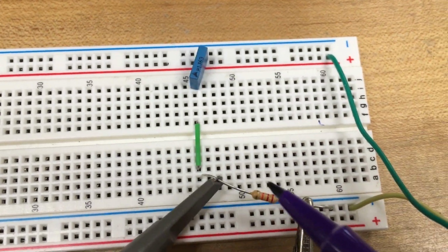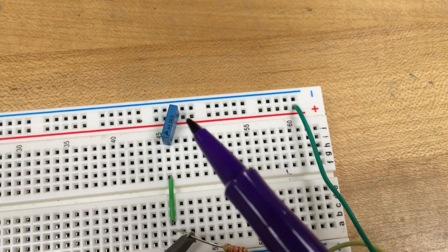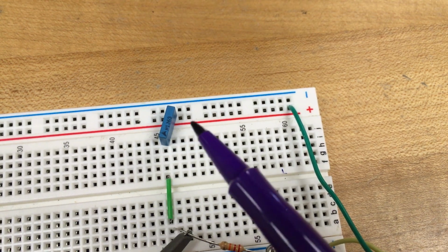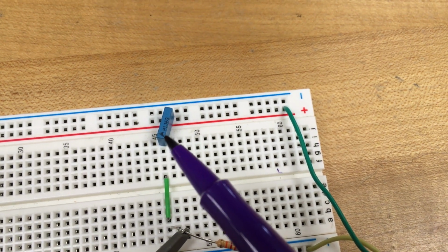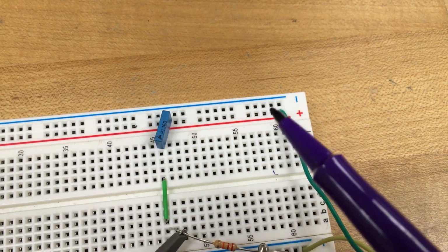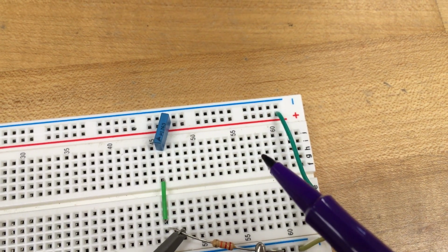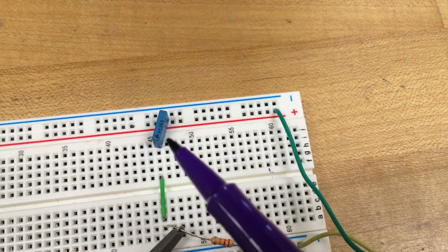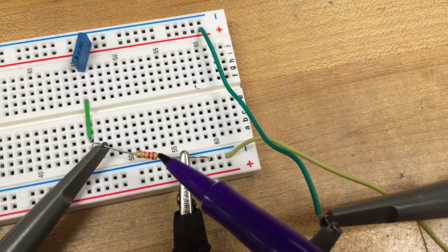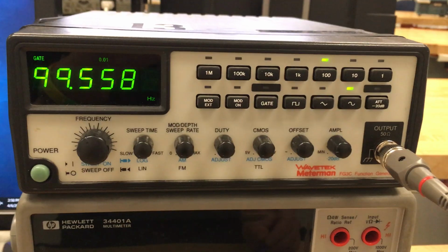So there's our seemingly very simple circuit. Because the capacitor alternately accumulates charge when the voltage wave is rising and in a particular direction on it, and then allows charge to flow away from itself in the opposite direction when the voltage falls towards 0 and is getting ready to go below the axis, to negative, this thing will shift the voltage signal that we read across the resistor relative to the voltage signal from our power supply, okay?